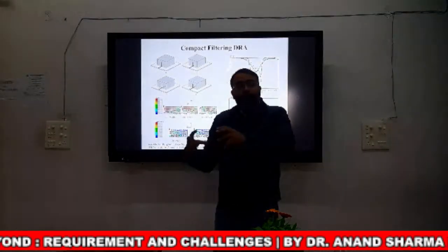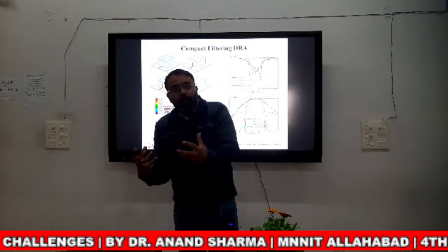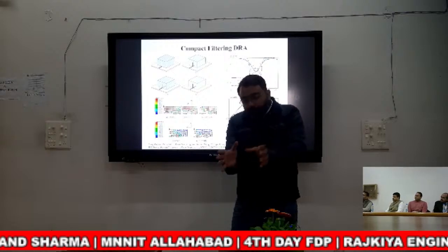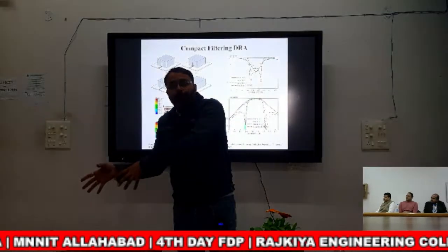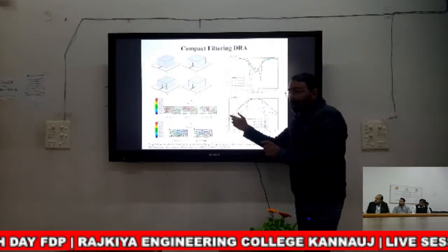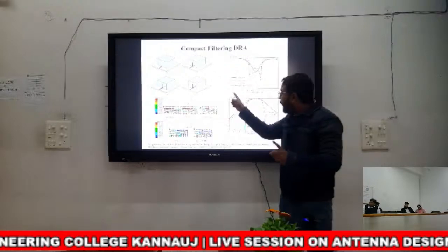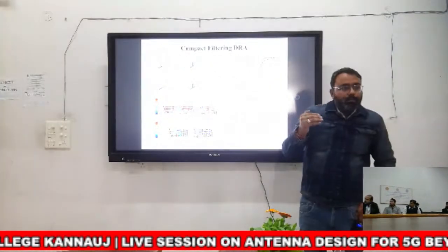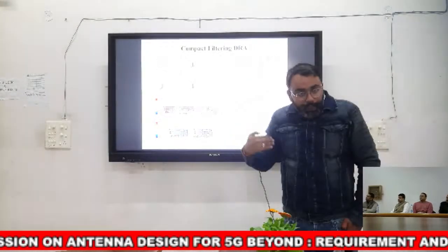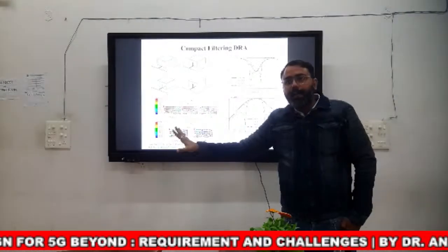Similarly, the antenna gain has a unit of dBic also. dBic means you are comparing your antenna gain with some isotropic circular antenna. So an antenna is a passive device, but we are using the term gain because you are comparing your antenna's radiation intensity with respect to some standard antenna.